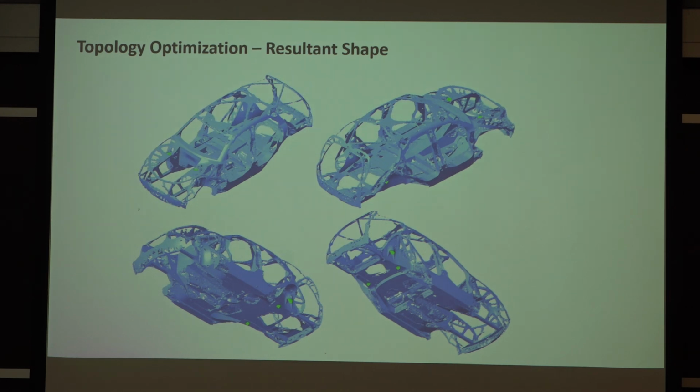So how big is our design space? Someone yell it out. 2.3 million. That's how big the design space is, 2.3 million. The optimizer that we used then went through and tried different values of these densities for each of the elements between 0 and 1, subject to the constraint that we don't have the same amount of mass as we did originally, and then strategically placed mass in appropriate places so that the aggregate strain energy of all the elements in that volume would be minimized.